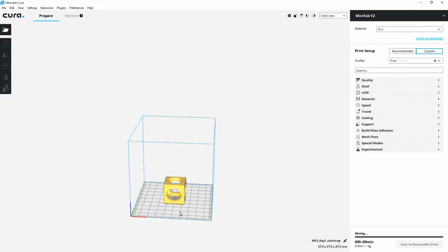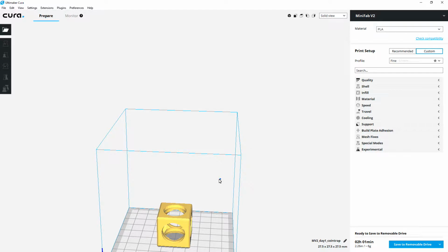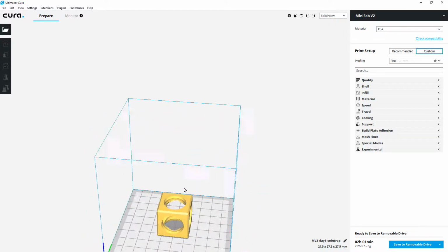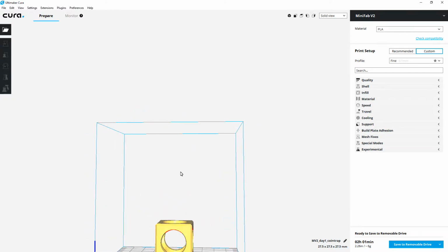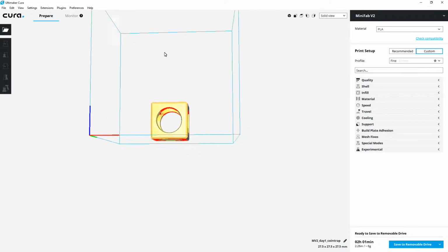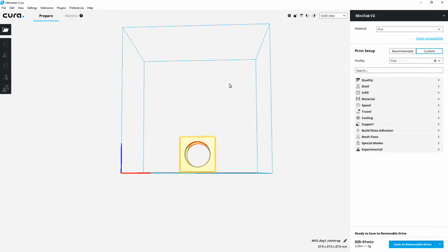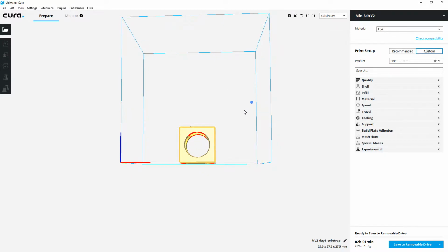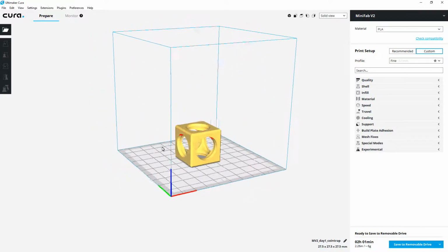Nice. So if we roll up and down on the mouse wheel, we can zoom in and out. And if we hold the right mouse button and go side to side, we can pan around and look at it. And if you want to adjust what the camera's looking at, which seems to be right about here, you can click the mouse wheel down and move that. And that will translate, instead of rotate, everything around. You can put that where you're actually looking. And then your orbit follows that point a little bit better.